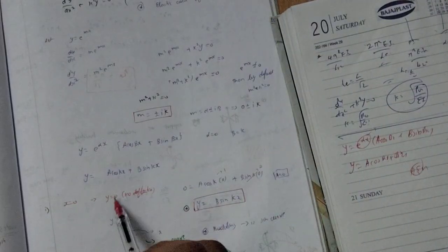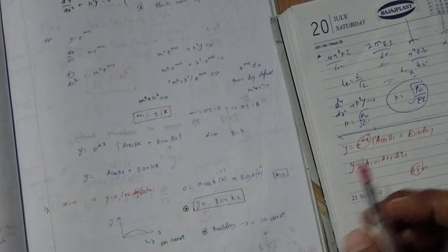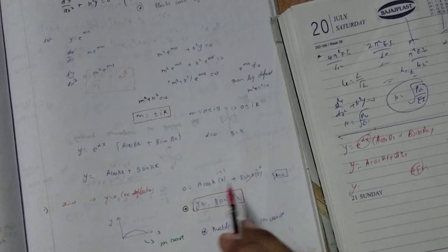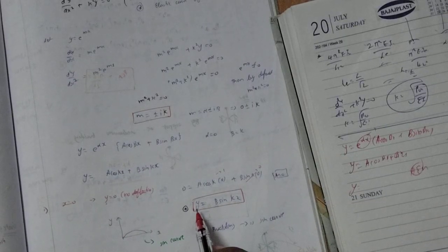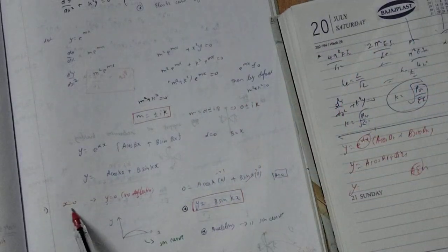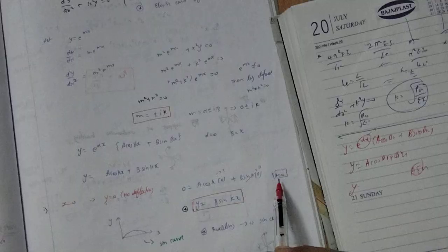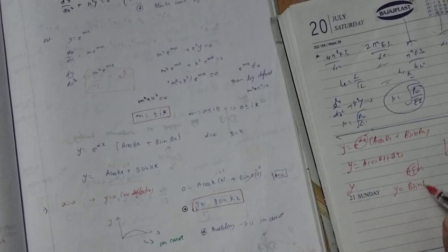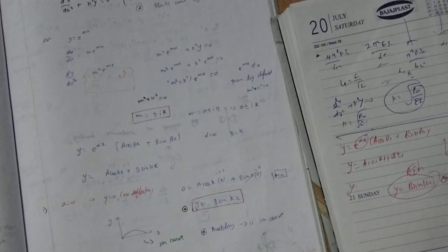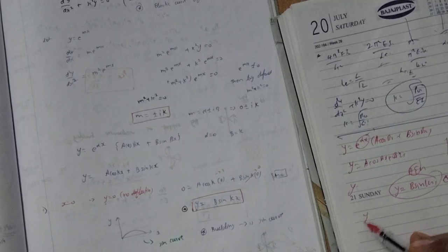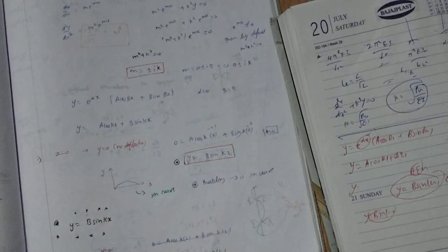Whenever y equals 0 at the end point, where x equals 0 and y equals 0, no deflection happens, and so A equals 0. So the deflection y equals B sin kx. The deflection follows a sine curve: y equals B sin kx. Whenever x tends to L, y tends to 0.